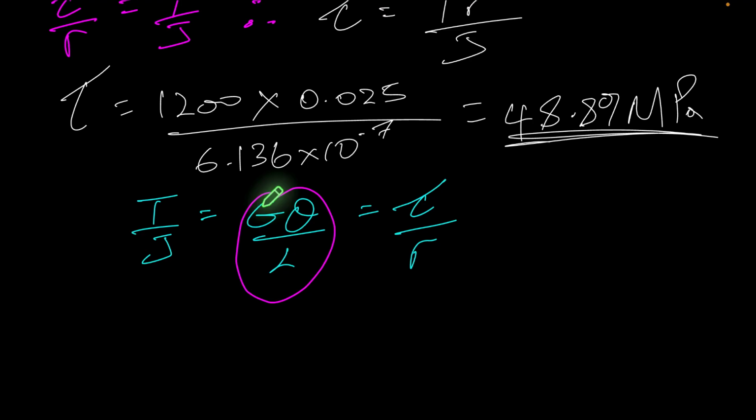We have modulus of rigidity that's given to us, that's 90 gigapascals. And we also have the length of the shaft, which is represented by our capital L there, which was 0.7. So what we need to do then is to determine if we're going to use this chunk of the equation or this chunk to pair with that bit that we have there.